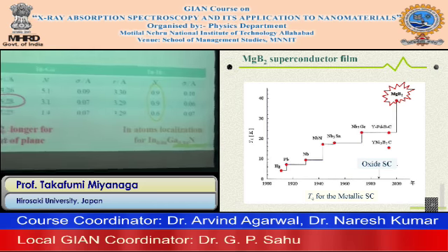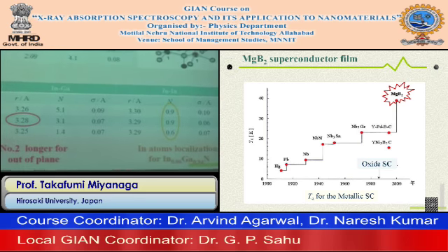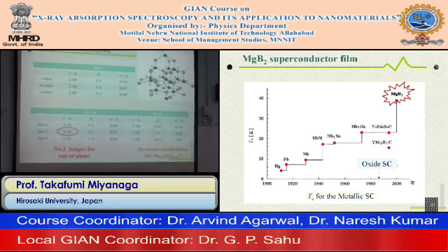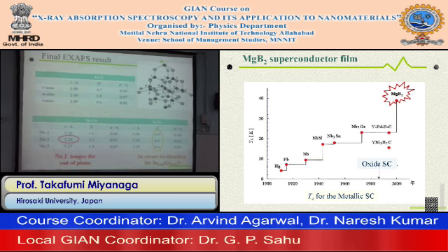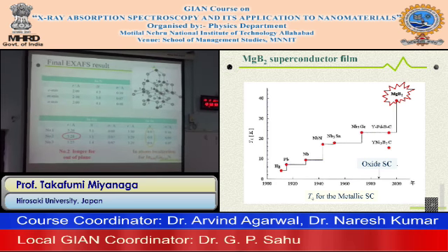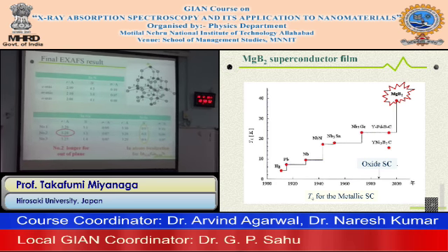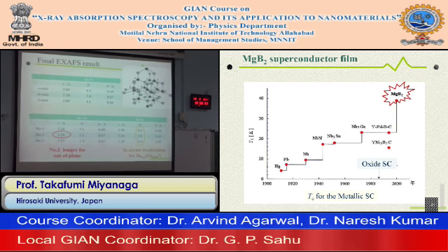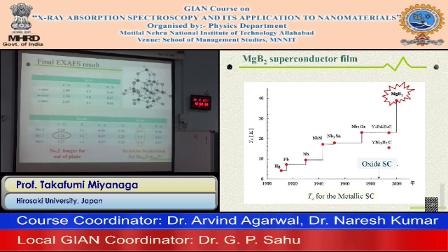Only that layer produces the emission colors, but all of the indium atoms control the gap energy. With much indium the energy gap is very small, and with smaller indium composition the gap becomes large, and the color changes to blue.